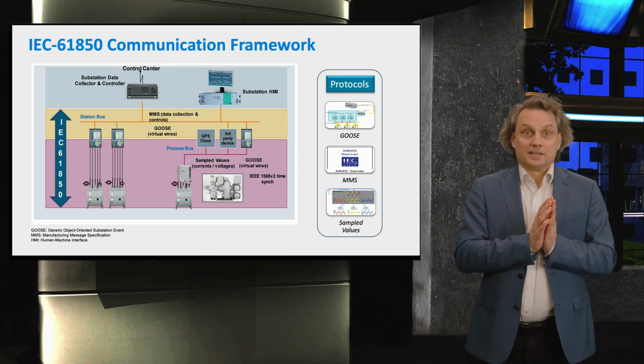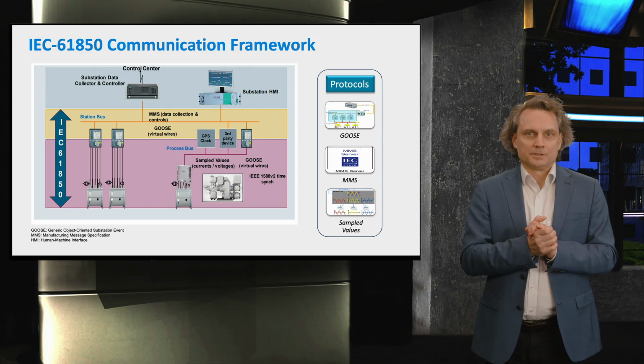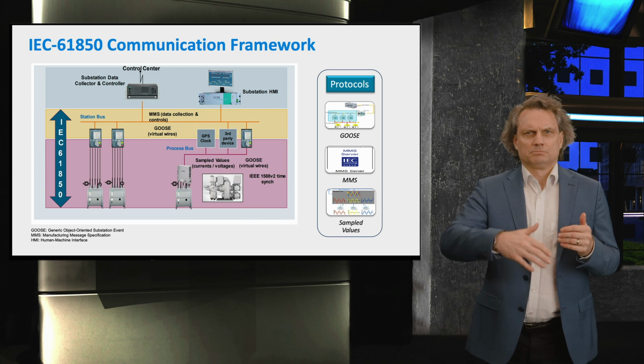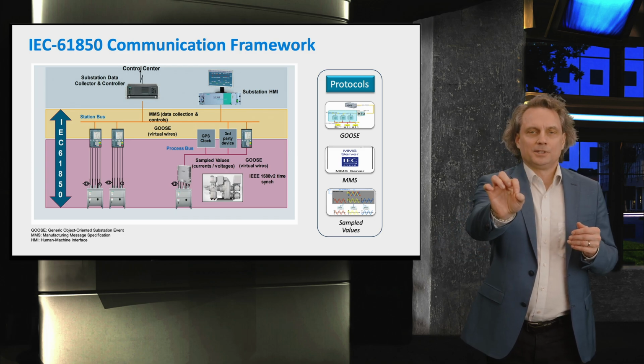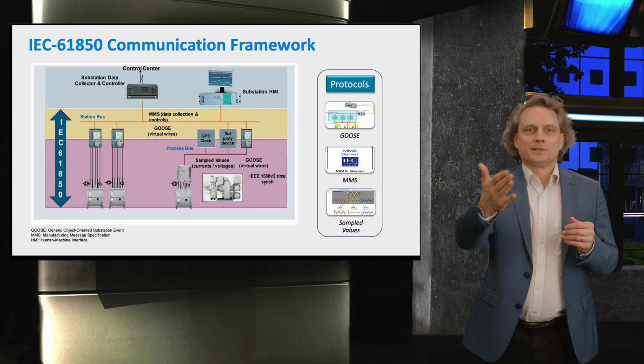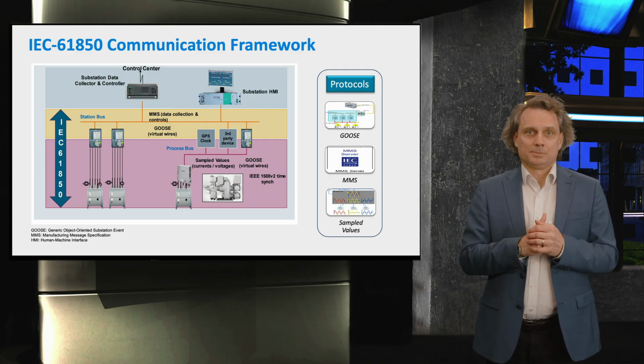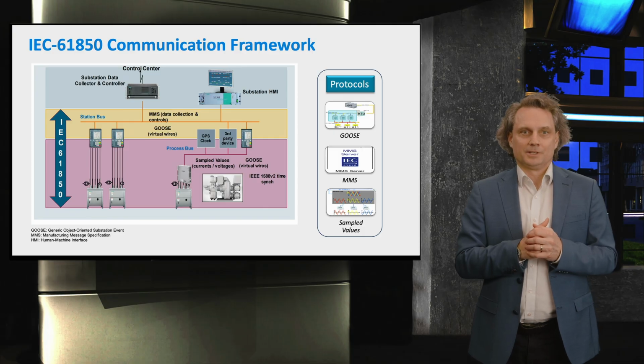Sampled Values, SV, is another such protocol. It's typically used for measurement data streams. You subscribe to certain data points, and these measurements are then streamed to you. Classical examples are voltage, magnitude, frequency, and so forth.